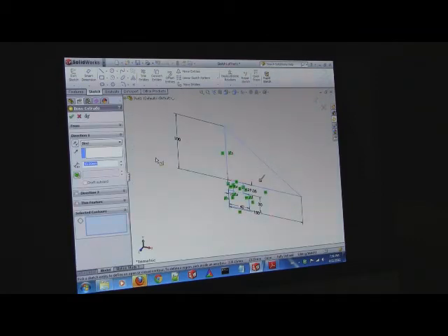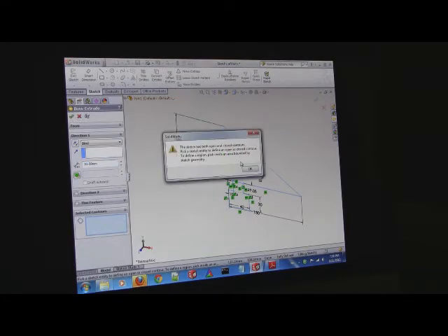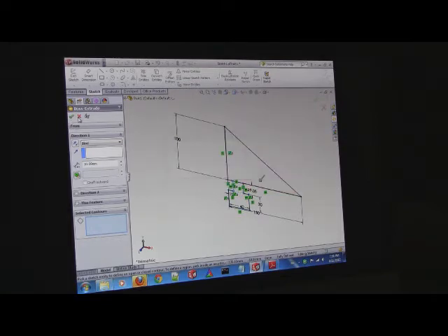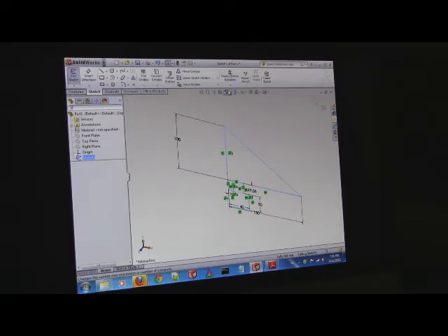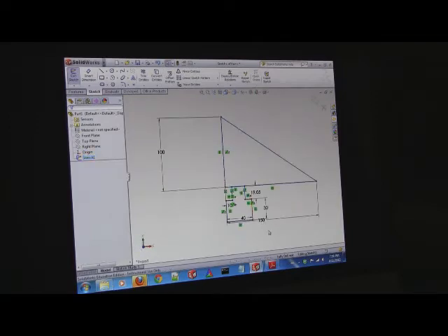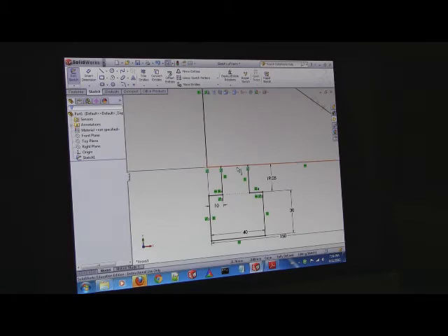Okay. You see how it didn't turn yellow? It's angry. We're experiencing the wrath of SolidWorks. And if I hit check mark, it says the sketch has both open and closed contours. Okay. So I hit X, fine. I go back normal. Does anyone know what's wrong with this picture? That right there. Does anyone know how to get rid of that?